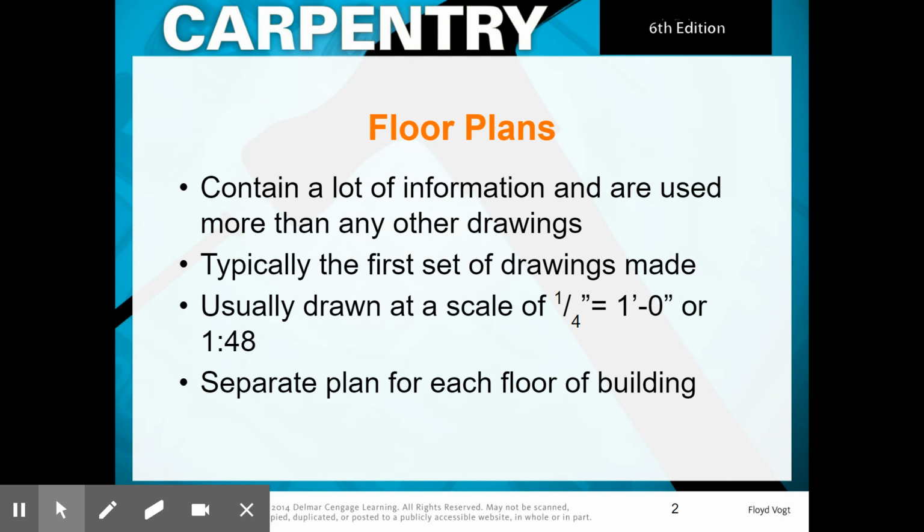Each floor of the building will have a separate plan. So if you're working in a structure that has 9 to 10 floors, always make sure that you're looking at the floor that you're on, because if it's a commercial building, the fit outs for the offices and the details could all be different.